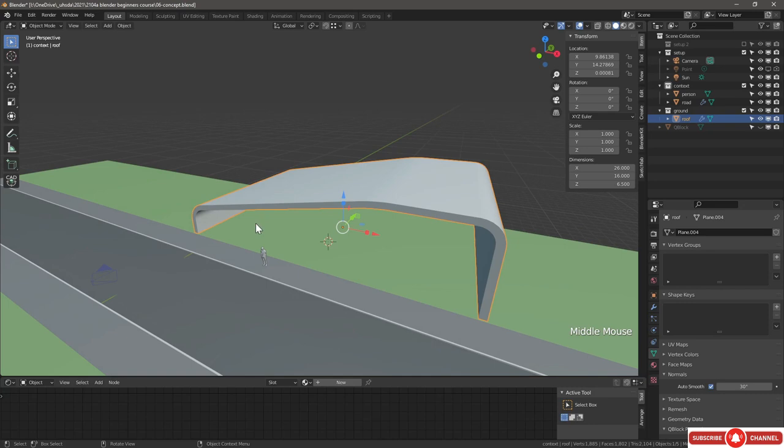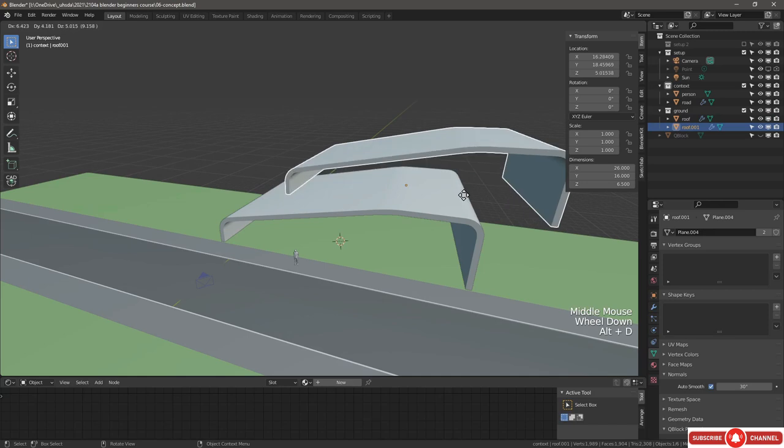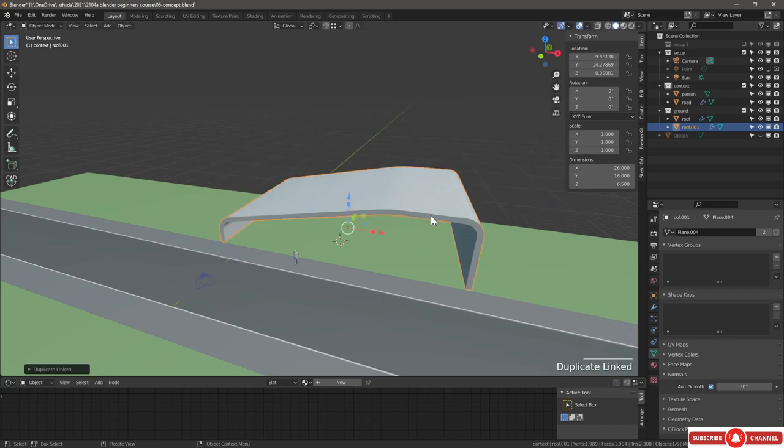So now we're going to use this geometry with a link. So we're going to create a linked duplicate. So Alt D to duplicate it, and then press Escape. We want to make sure that rendering is unchecked because we're going to use that to subtract our curtain wall. We don't need to draw it precisely as we have it here, and it's going to be also non-destructive, and we want to make sure that we can control that easily. So the easiest way to do it is to have linked geometry to the original roof.